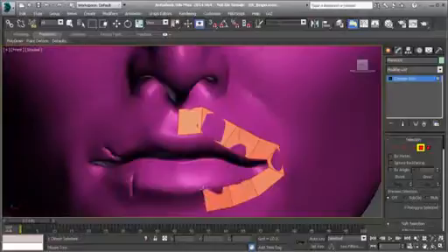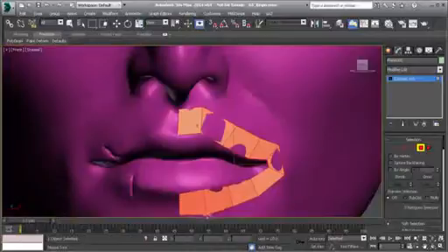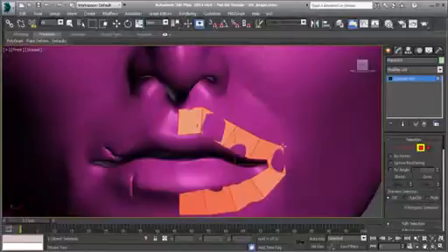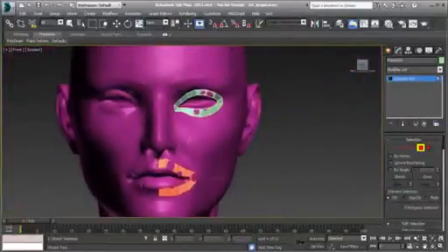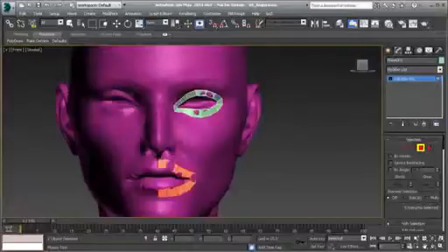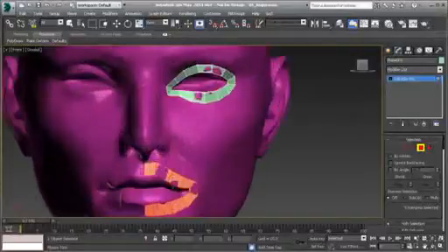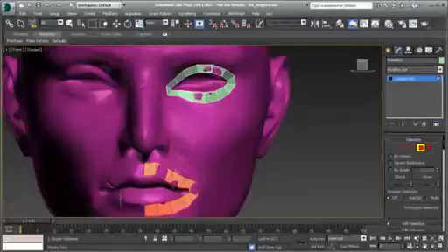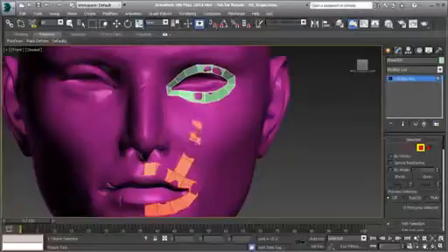So if you want, you can actually hold down Shift, kind of drag this up, and I'll just start creating a few polygons here. Once I get up to about here, I'm going to hold Shift, Control, Alt, and then left click and drag from that edge to this one. And then hold Shift, Control, Alt, and start moving the individual points around, trying to follow the flow of the face with these polygons that we've just created. Okay, so we're getting all of that together.